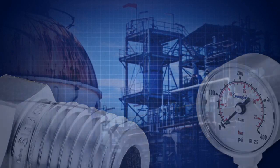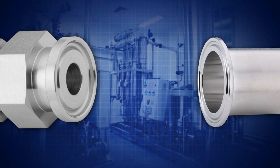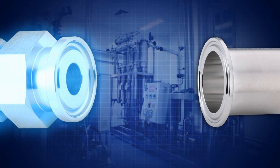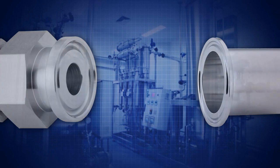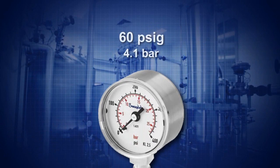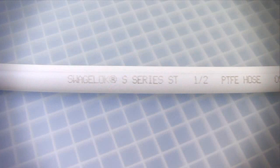An example of a pharmaceutical setting is a system that has a 1/2 inch sanitary flange on one end and a 3/4 inch sanitary flange on the other end. The system rating is 60 psig or 4.1 bar. The hose type is fluoropolymer with a silicone cover.